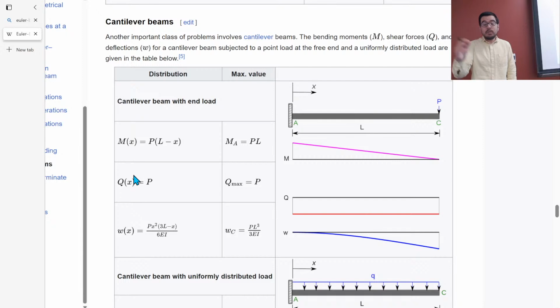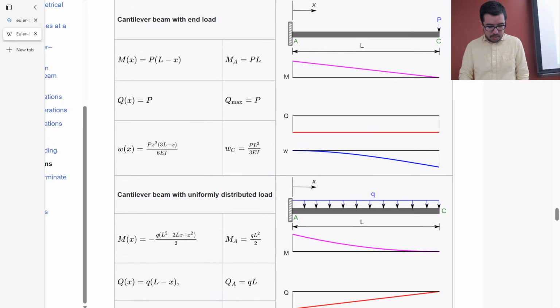I mean, if you have to, you have to, right? And I did an example in the previous session 24, where we did 4 integrals, all right? But if you can avoid it, avoid it. Start with the moment. Get an equation for it, because especially if it's a statically determinate system, you can figure out the moments across that beam without too much difficulty.